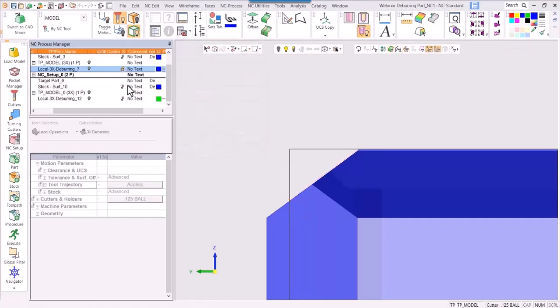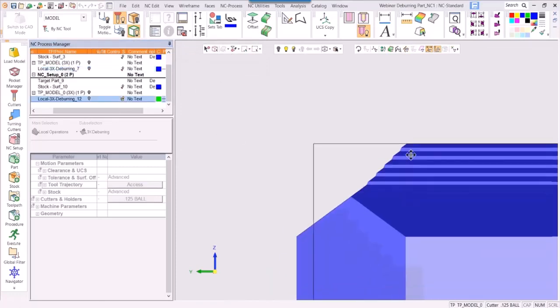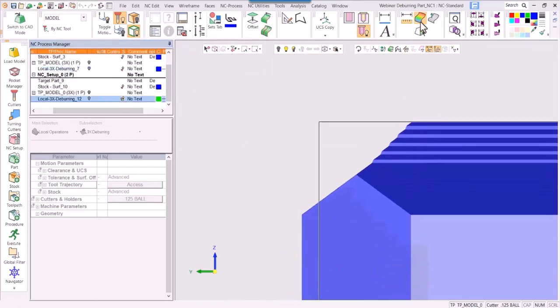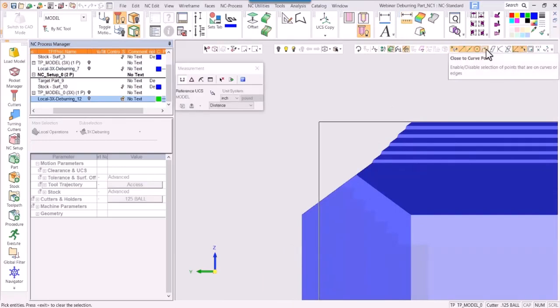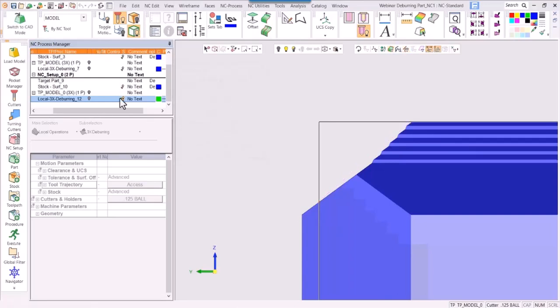That's under width. So depth, you're going to get a lot deeper path here. You can see that that's quite a bit of difference. About 50% here on just the 10 thou with that 90-degree corner. So just be aware of using constant depth or width if you choose to use one of those.